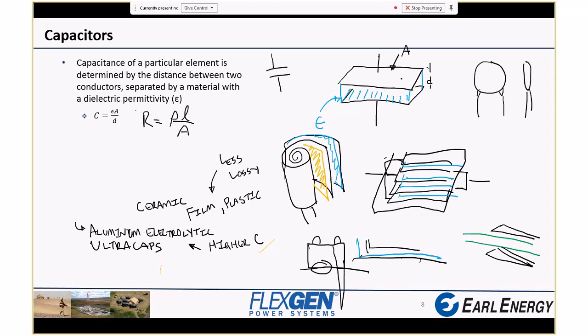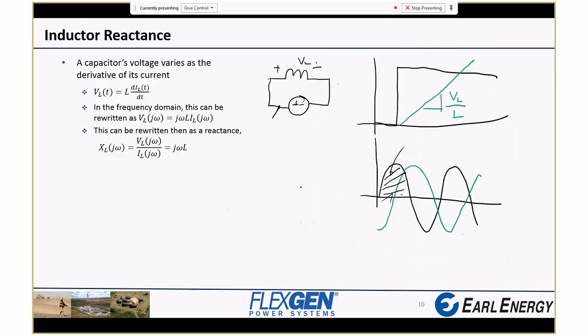Everyone will have a little bit of capacitance sometimes just because there are conductive parts near each other. Everyone's going to have a little bit of inductance just because there are leads. And like we said before, a wire has a certain amount of inductance. The area enclosed by the leads connecting to a PCB gives a little bit of inductance. And everything is resistive because nothing is perfect in this world. So that is probably enough for today.